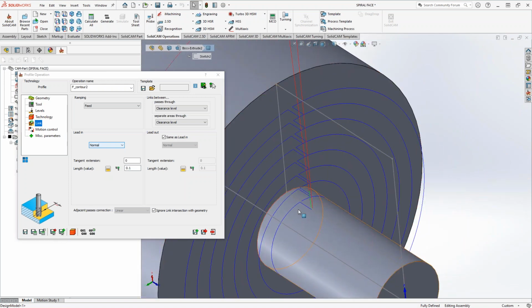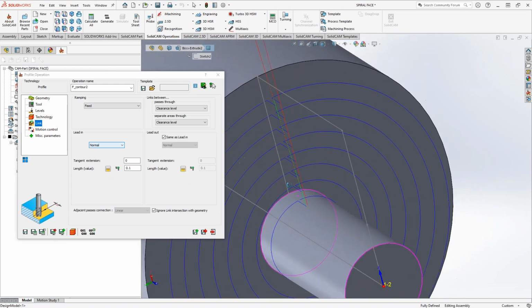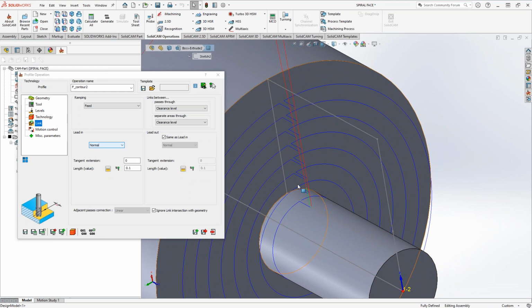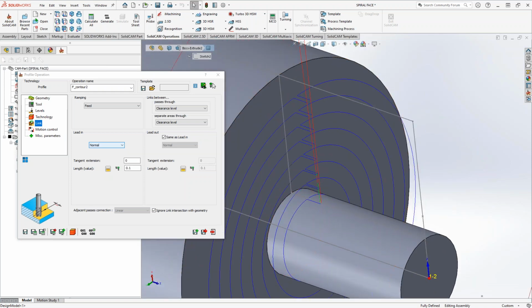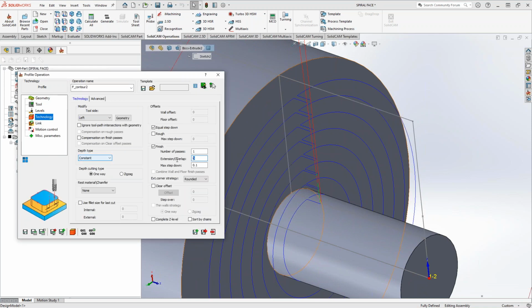Now, the radial nature of it looks like it might actually be stopping and starting a little earlier and a little later, only because, again, because we're wrapping it, it's not the best projection of the toolpath. I probably wouldn't really do exactly what I want to do here with a profile. But if I want to account for that, remember we have this overlap over here.